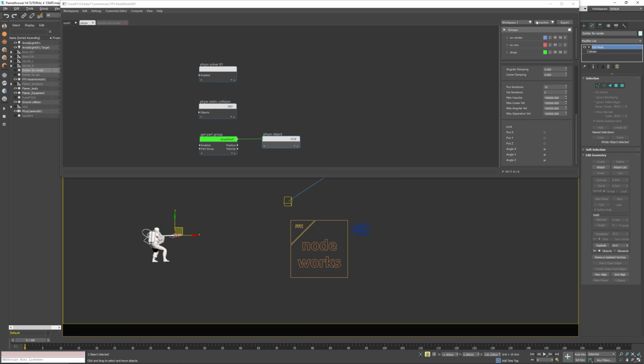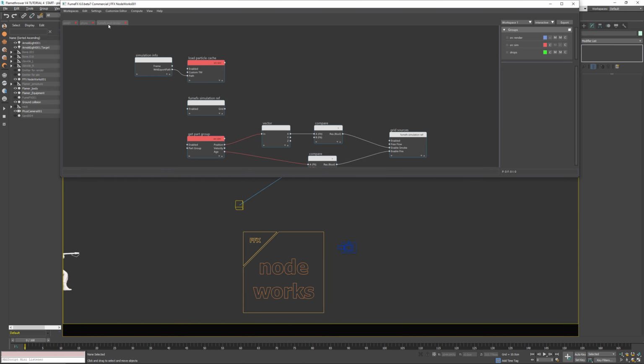Now since everything is set up here, I'm going to go to caching. You change your path and you hit the export button to cache all the particles here. So we use cache particles, and now I can disable those two tabs, and I can enable FumeFX and render, a tab where I have the simulation info node that provides the workspace path to load the particle cache path.